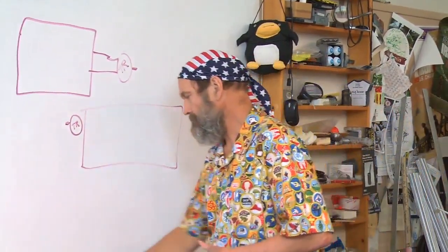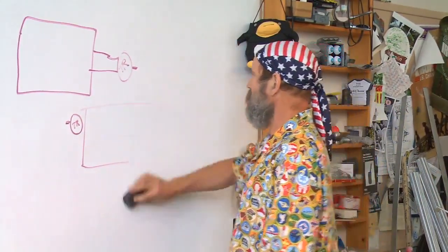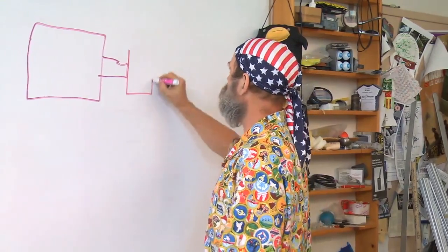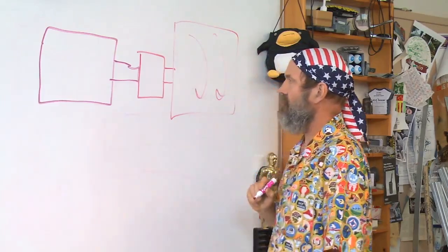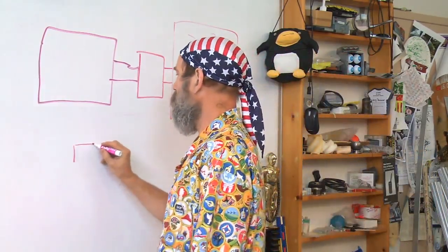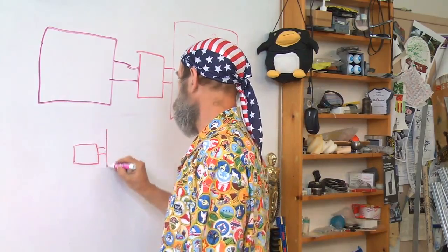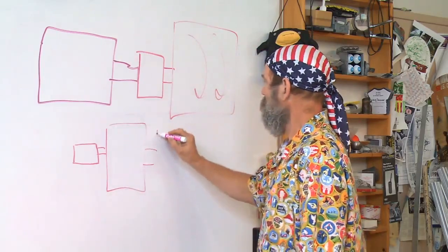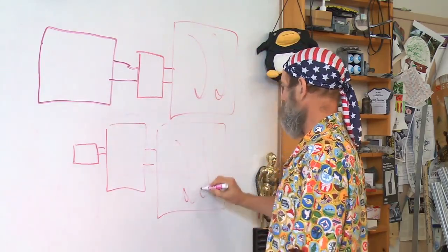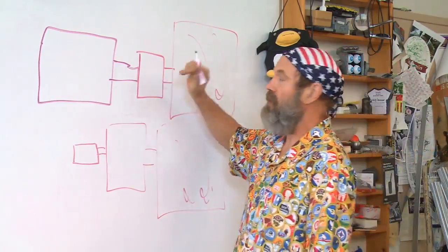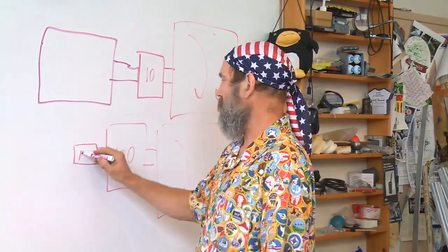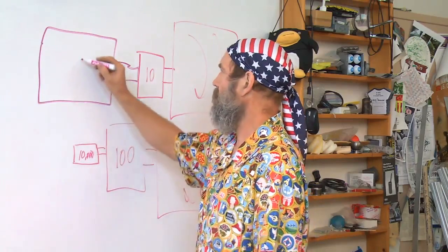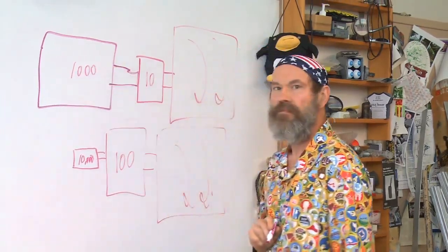And a more realistic scenario is, now that we've driven that point home, here's your transmission output. Let's say this is the big giant spinny thing you've got to spin. Or do I take a smaller, very high-speed motor and some other kind of transmission, also the same size, big output spinny thing? Where, for example, this is some transmission ratio 10, some transmission ratio 100, and this thing here goes 10,000 RPM, and this thing here only goes 1,000 RPM. Okay?